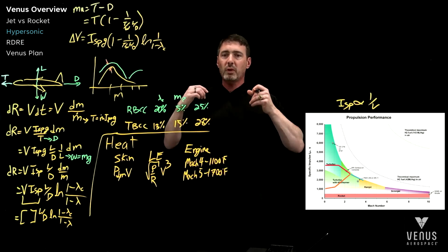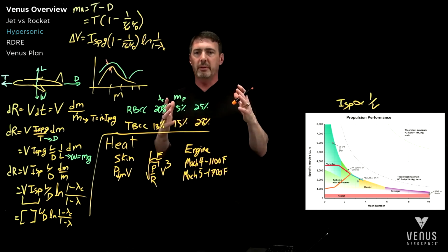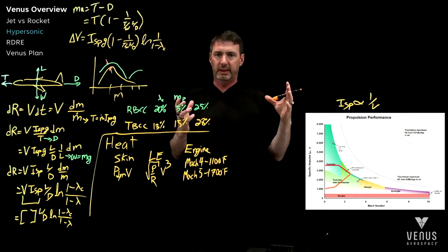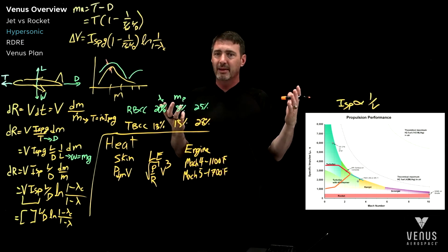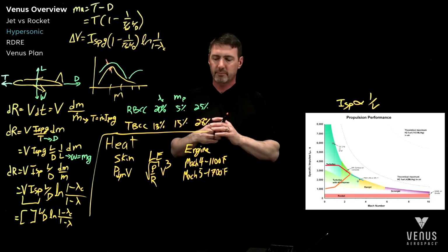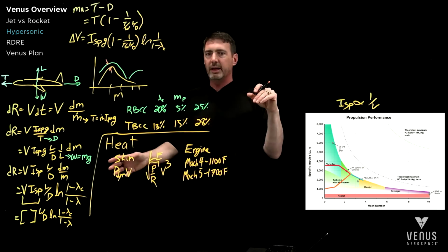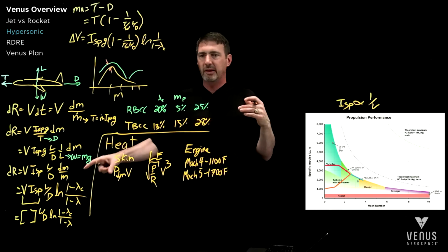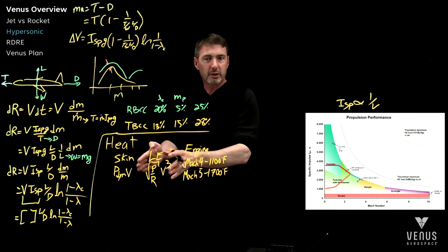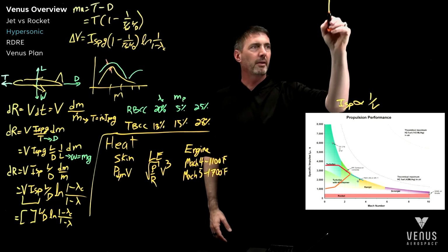And so when you're thinking about going fast, let's say it this way: if I double the flow rate of fuel into my engines, if my engines are twice as thirsty, but I'm going twice as fast, then there's no change in how much fuel I used in that situation, right? And so we actually need to finish with the drawing of lift to drag and how it's changing with Mach number. Because you see, lift to drag is important here. I've talked about the drag term based on your choices of leading edges. So really we need to finish with the lift to drag diagram.